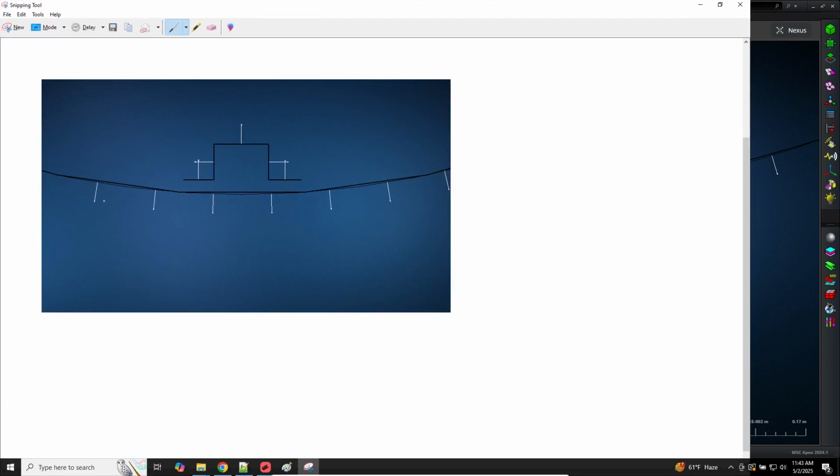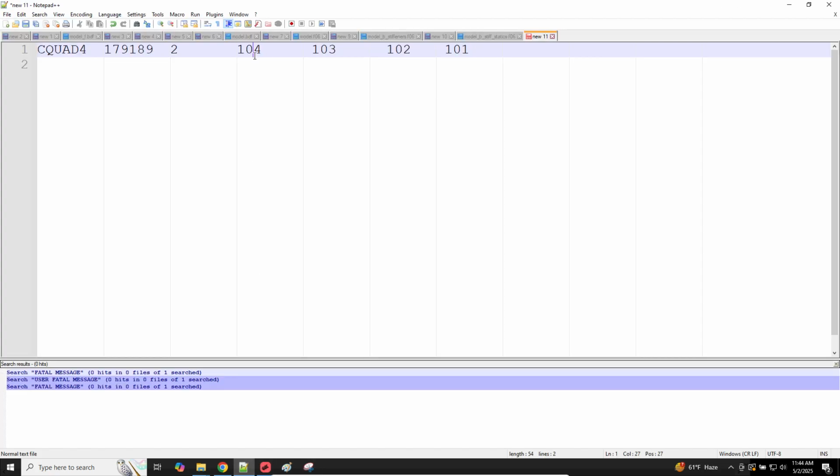We'll say, you know what, for the wall, I kind of like this. I like this is layer 1, layer 2, dot, dot, dot. I want this wall to also be in the same direction. I want this to be layer 1, 2, so on and so on, dot, dot, dot, until I get to layer N. So what we need to do is take this shell normal and flip it. We need to reverse it, so it's in this direction. If you recall here in the 2D elements, we need to reverse the order.